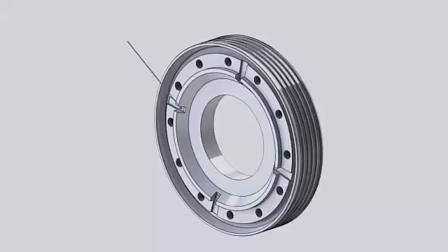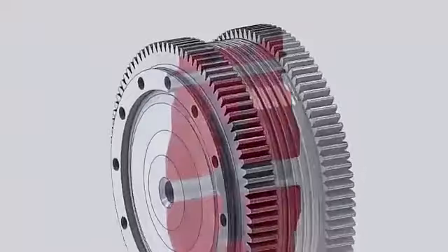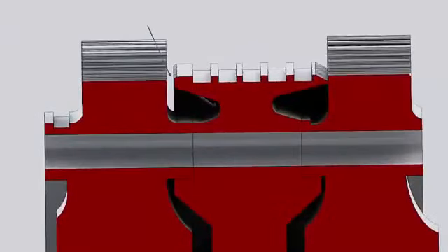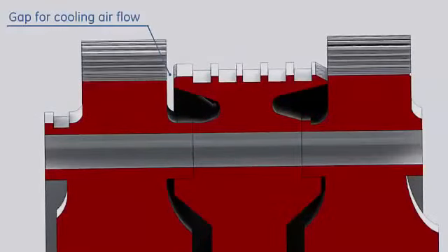The second wheel spacer is located between the second and third turbine wheels. Slots are machined on the forward face. The forward face of the spacer is machined to form a gap at the mating surface with the second stage wheel for cooling functions.